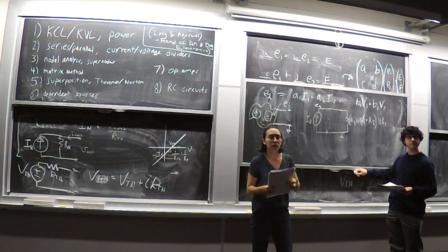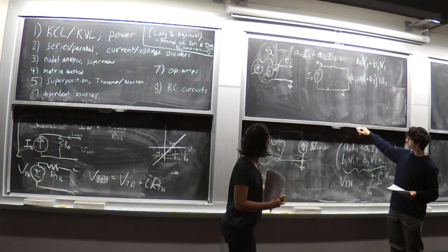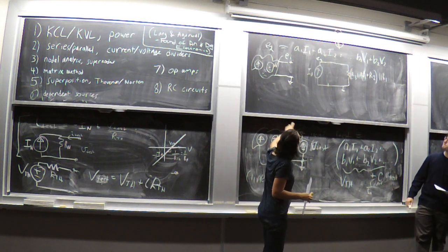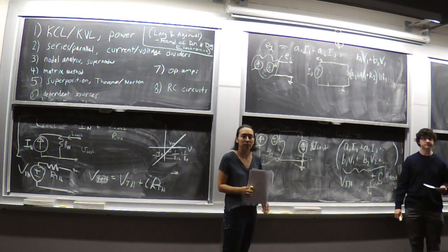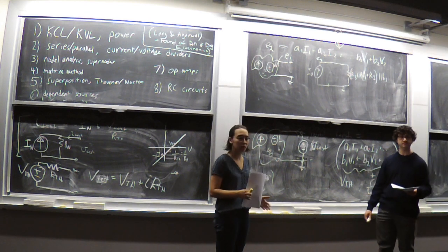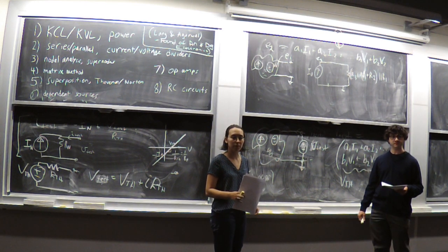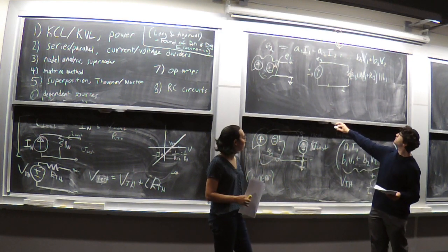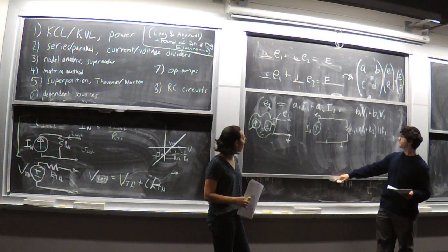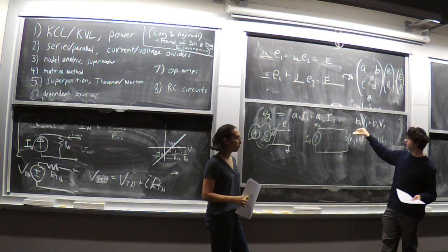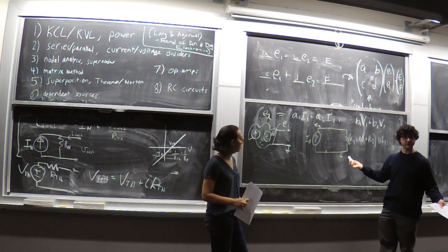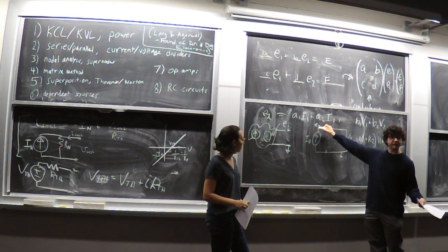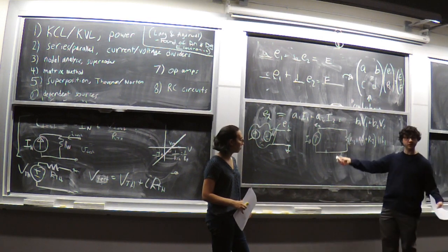Yes. Just a quick question on that. So, you compressed everything by seeing what things were in parallel and series with each other. When you need to find the equation for the node, do you have to re-expand? Because there were E2 and E3 and things like that. Yeah, so if you wanted to get what E1 and E3 were out of this, it doesn't exist in this current model of the circuit. So one thing you could do is break it down like this, solve for E2, and then slowly expand back out because you now know the value of E2.